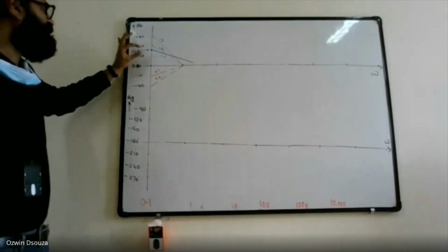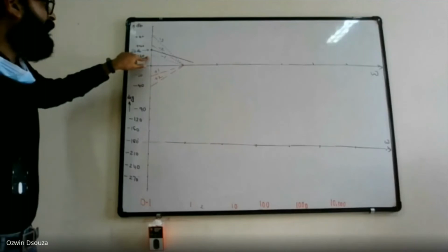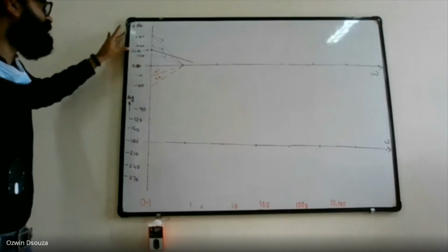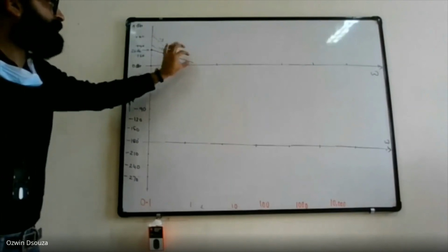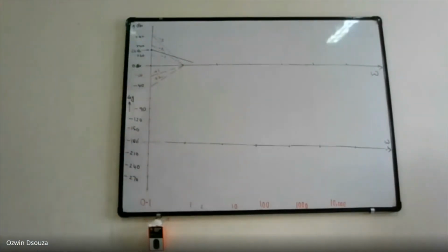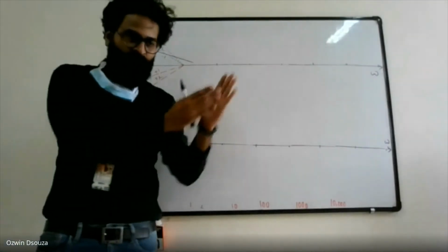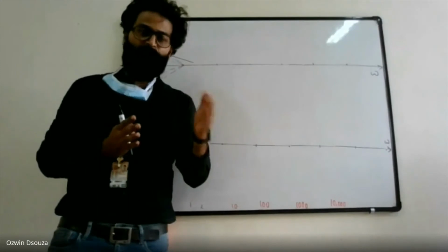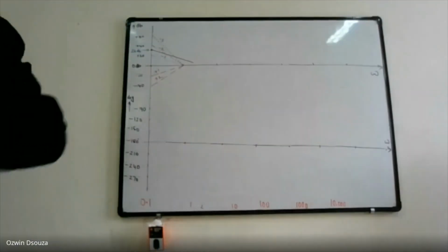Another trick is to just measure this distance from 20 dB, how many divisions it will take to reach 26 dB. Measure this distance, and at 2 radian per second, place that distance and just connect the 2 points. It is up to you. Or, like how you draw the vector diagram, you have to draw a parallelogram. In order to draw a parallelogram, you draw a parallel line from the reference line.